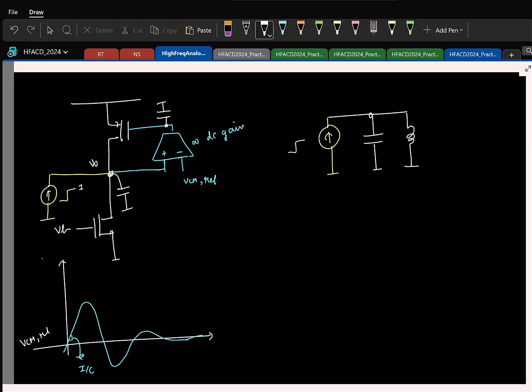I can add a resistor in series with the capacitor, inductor. Do you think the damping can be emulated by putting a resistor here? But do you think that models this circuit? In steady state, what can you say about the incremental output voltage in this circuit? 0. So here, in steady state, what will be the voltage? Steady state, capacitor is open, inductor is short, all the current flows here, it's I times R.